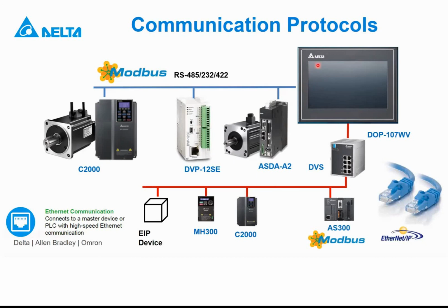If it's a communication sensor, maybe based on RS485, you can connect directly. But I think those sensors are also very expensive. In a traditional case, you connect your sensors to your PLC, then the PLC talks to the HMI, and the HMI controls everything that has to do with your machine. So that's it. You can go for AS300, which is more expensive than this. You can also go for DVP.